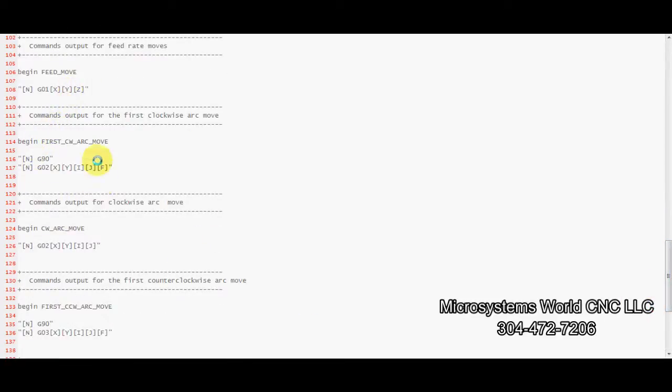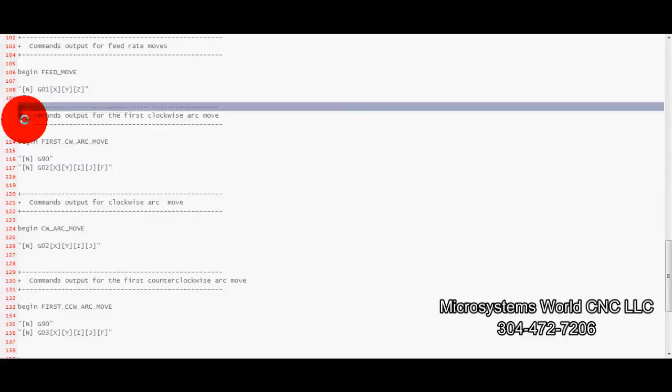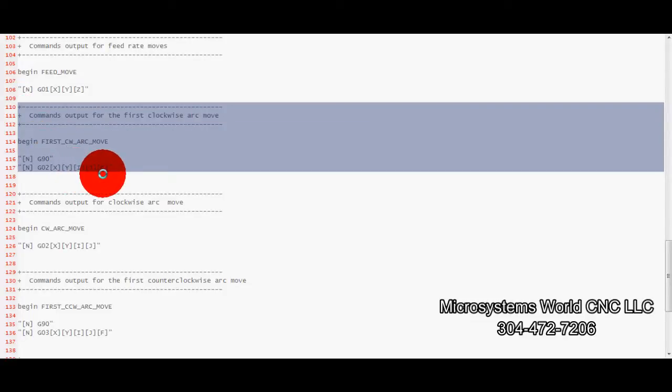Also, since we've already had our feed rate set up there, G2s are just clockwise arcs, and clockwise arcs are just feed moves. So the feed rate would be set up there above, as I showed a while ago. So I do not need this section either. And by the way, you see I'm getting rid of another G90 there.